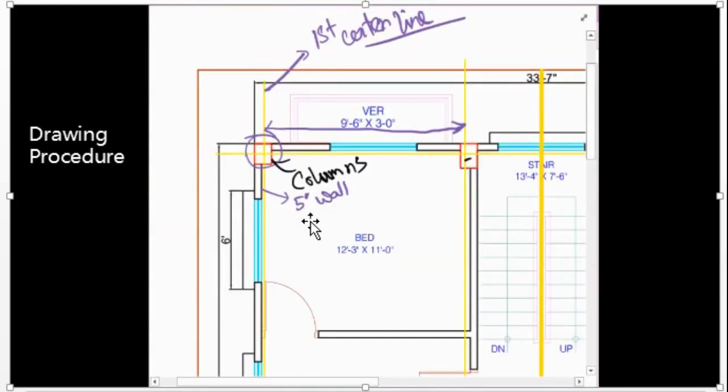So this is a 5-inch wall, as you know. If you see the column dimensions, typically we use say 12-inch by 15-inch. It will be given obviously. So in this case, assume 12 into 15-inch. Architectural drawings, most of the time, don't give the actual dimension.